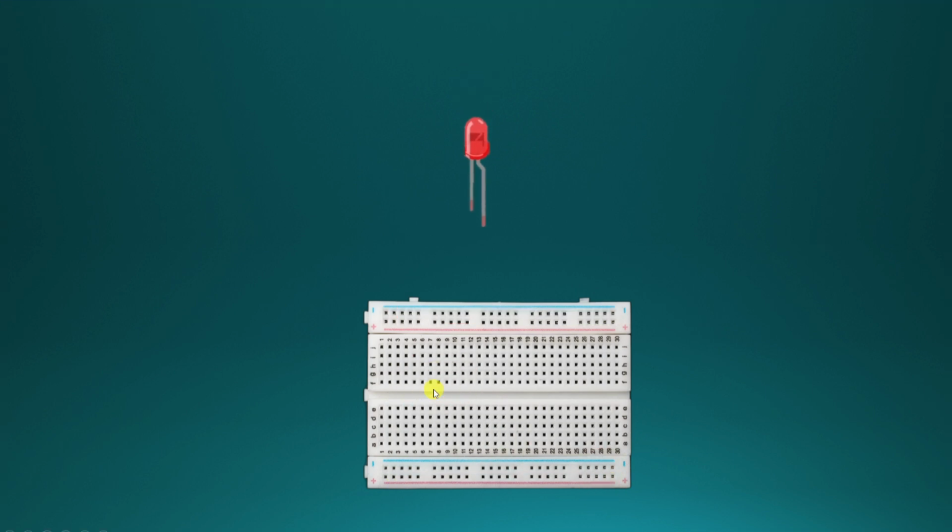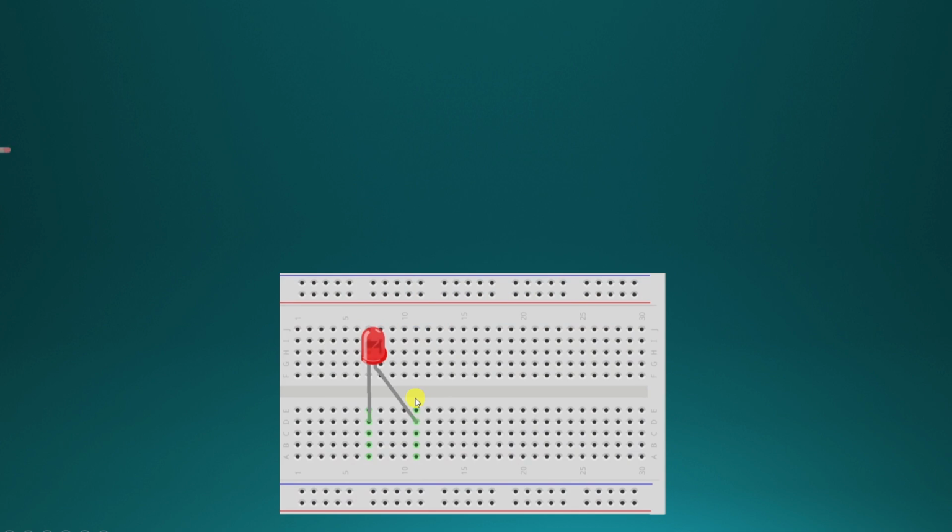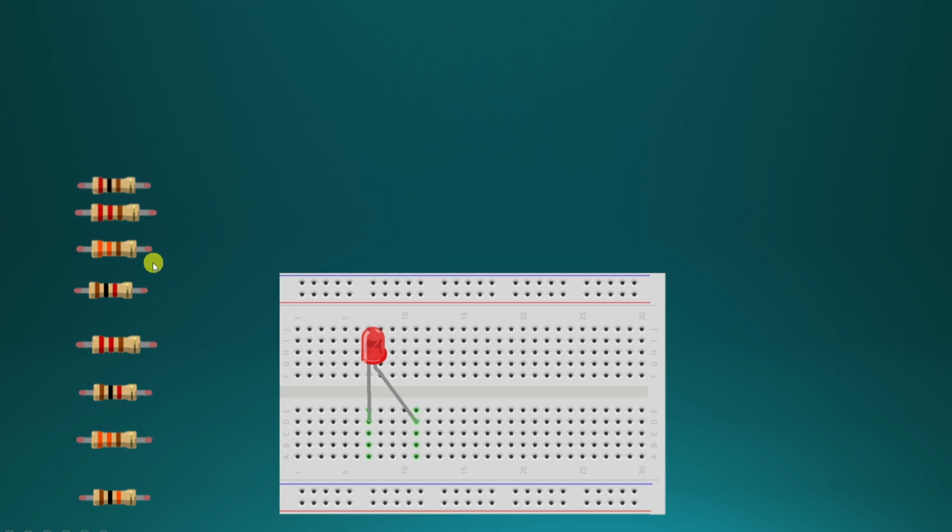While interfacing LED with Arduino Uno, we always use a resistor since the resistor limits the excessive current flowing from the Arduino pin to the LED. So it will protect both the Arduino Uno as well as the LED. Multiple resistor values are available, 100 ohm, 1K, 100K, but which one should we prefer while making the hardware connections?